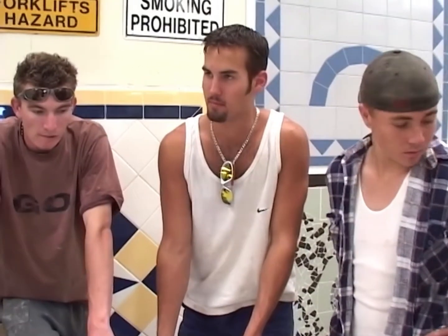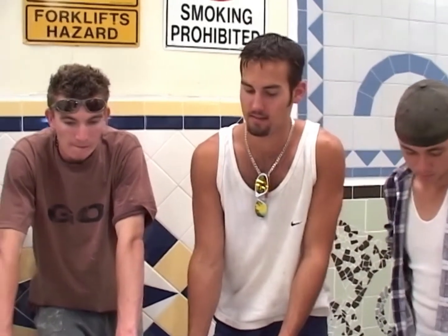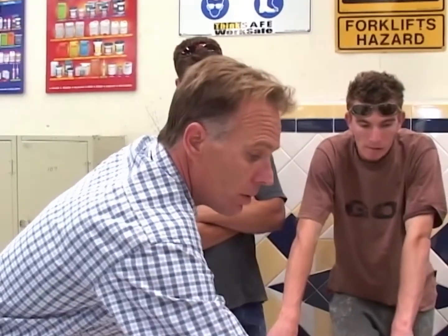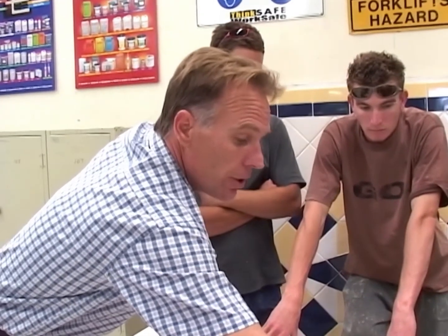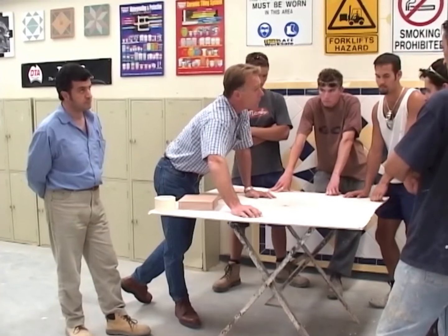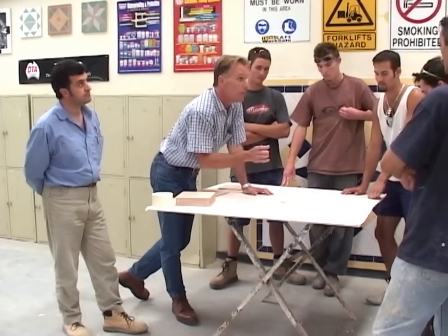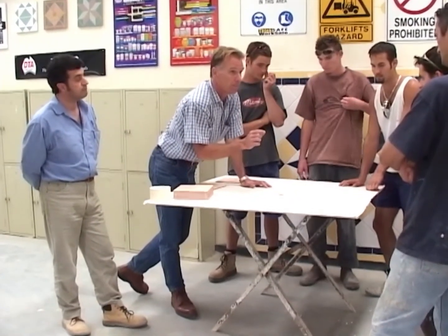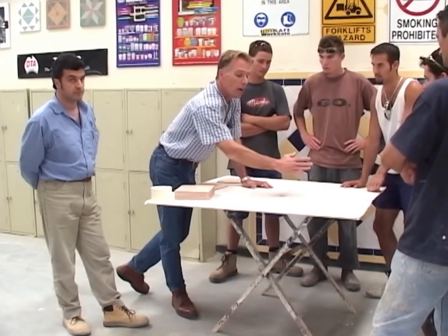What happens if the 15 pieces don't fit? Okay, good question. Once you've divided your quadrant into 15 pieces and you've come up with 37.8 mil, you've set your scribe and you're going to work your way around to evenly get each piece. If you end up at 3 o'clock with an extra 8 or 10 mil over, if you're working with 15 pieces, obviously you're going to have to open up each piece by about a mil, and that'll compensate for that 15 mil over the whole distance.